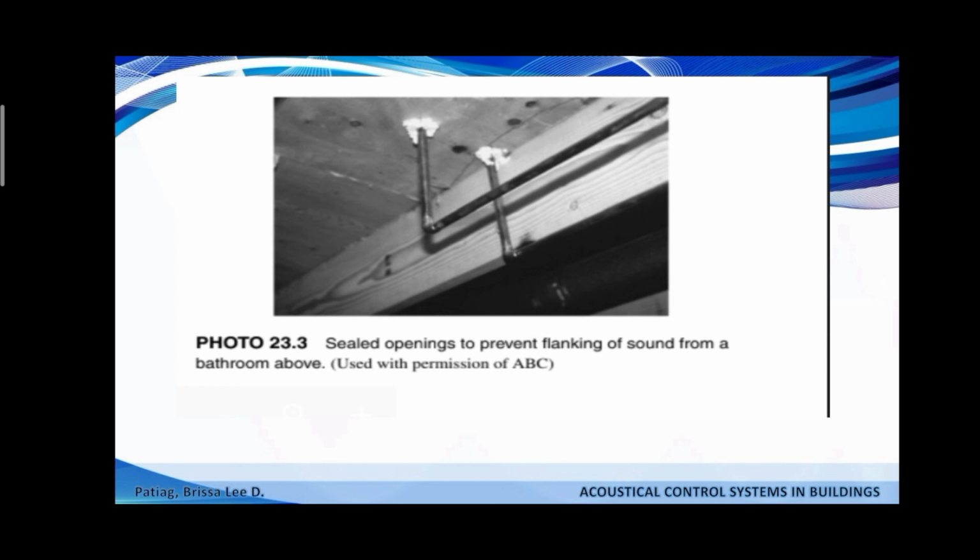So, at the ceiling level with such a system, sound can be transmitted up through the suspended ceiling from the plenum space. Through the plenum above the partition down to the other side, extending the wall to the bottom side of the floor eliminates this problem. But it is more costly and offers less flexibility with future renovations.